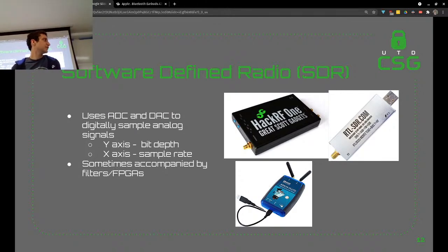So the cool part about this talk is SDR, which is software defined radio. Basically, instead of having something like this where you have to tune it to a specific frequency, you just take everything. You say, just take a bunch of samples of stuff. So it's like, your antenna is giving an analog to digital converter a signal, a different voltage, and you just take a bunch of samples of that. You say, what voltage is this at this time?